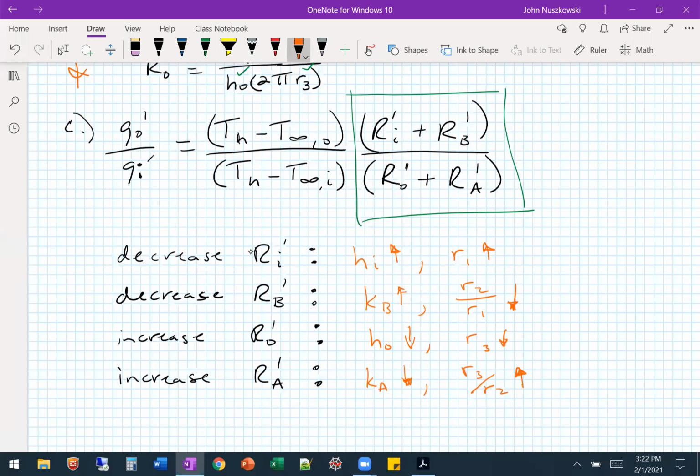Okay, so that kind of tells us now the parameters we want to mess with. So this would be higher insulation. That's that KA, making its thermal conductivity go down. That's kind of like an insulation, right? And having higher thickness insulation, right? This is showing us having thinner, high conducting material would be beneficial. High thermal conducting, okay? Or on the outside, having stagnant air, like not as much of a higher velocity, so not high convection, right? So keeping that velocity down, having more stagnant air. Okay.